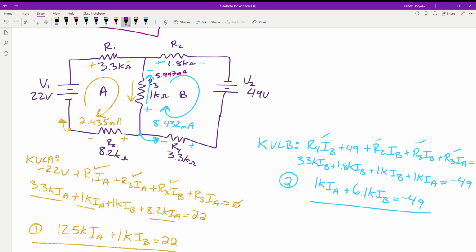Okay? So then, when we type in the answer, remember we read top to bottom, left to right when we measure polarity. So when we put in our voltmeter, oops, let me make that a little bigger. That's how we'll hook up our leads, and it's going to show negative, because with our voltmeter we're reading top to bottom.